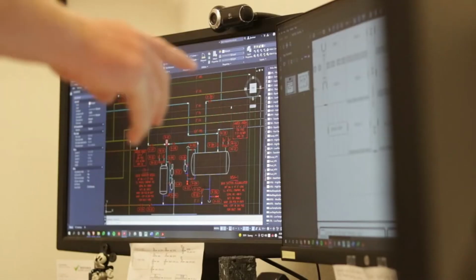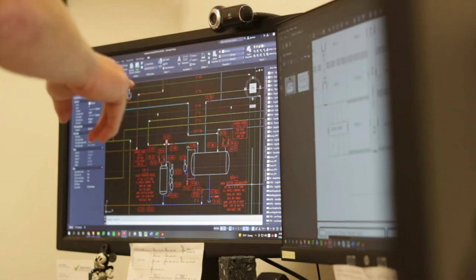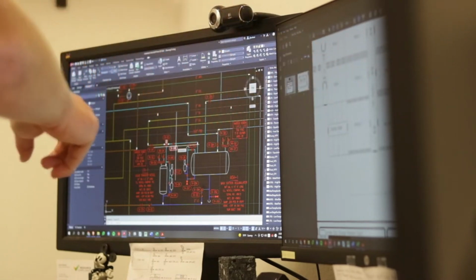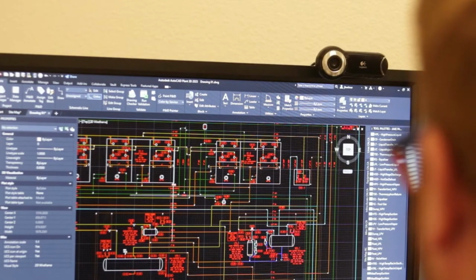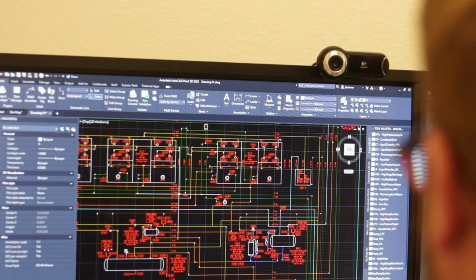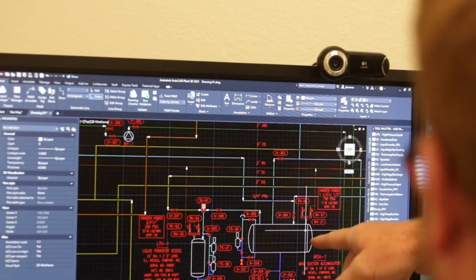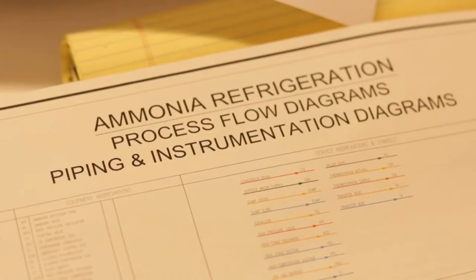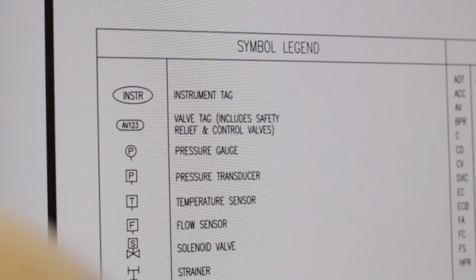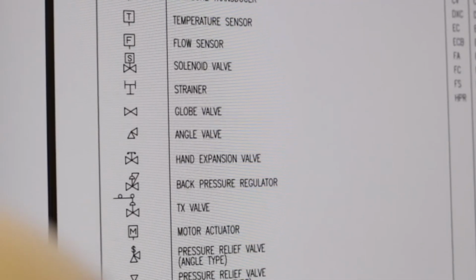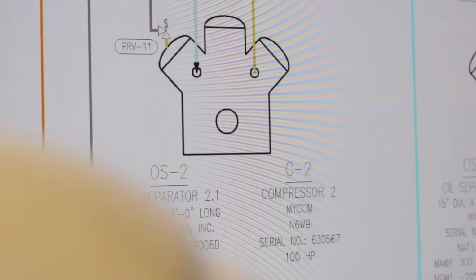The term P&ID is an acronym for Piping and Instrumentation Diagram. As a drawing, a P&ID includes all the process equipment, interconnecting pipes, manual valves, control valves, and process-related instrumentation as necessary to fully represent and understand the system. A good P&ID will be equipped with a clear legend of symbols to assist in diagram interpretation. P&IDs utilize detailed annotations to describe the pipes and equipment.